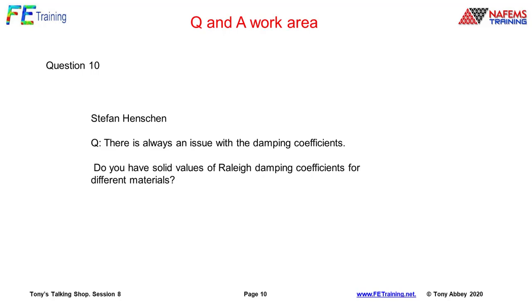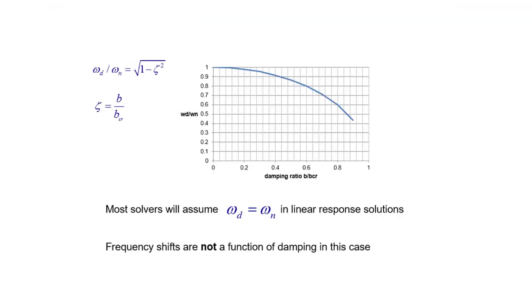Anything above 10%, we're getting into the nonlinear regime where the damping is starting to shift the frequencies around, going back to Noel's question. So we talk about damped natural frequencies as opposed to undamped natural frequencies, and then we get a shift of frequencies at that point.